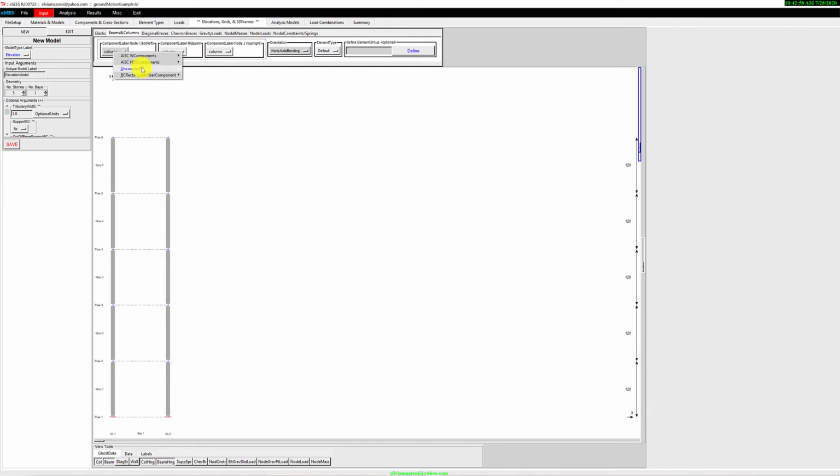Let's go to the beam cross section here. And now you've got to make sure that the other points are also beams. So you actually can define 3 different cross sections along the length of the element, even if you have more integration points here. Now I've got the beams, so I'm going to shift and select all these beams. Yes, I want to select these. Perfect. Done with the model.